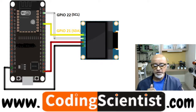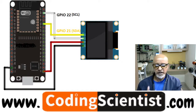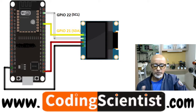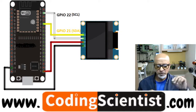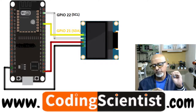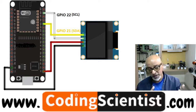Now, this SSD1306 is the name of the display and the name of the library, both are the same. There is also the SSD1315, and it is basically a 0.96 inch, or also a 1.3 inch display. That's the difference between the 1315 and 1306. It's just the size and the number of sectors. Basically, it's a blue OLED display module. At the back end it's totally dark, and when it glows it's kind of radium blue. You are going to see the live example anyway.